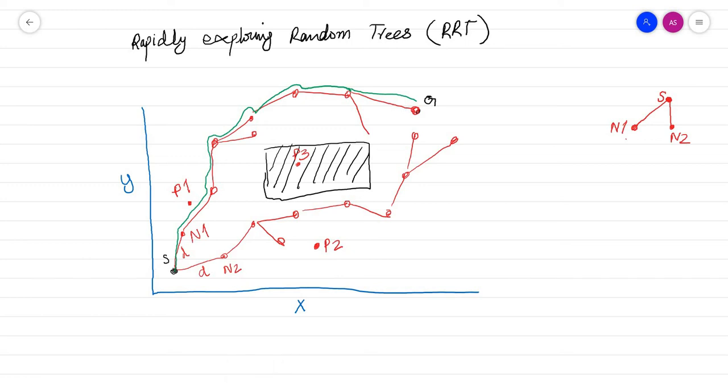This was a path that was found during the RRT algorithm, and of course I think this is not the shortest path or the optimal path. So the RRT star algorithm, what it does is that it rewires your tree. Okay, for example, if you found a better or the shortest point within the radius r, then you can rewire your graph actually.